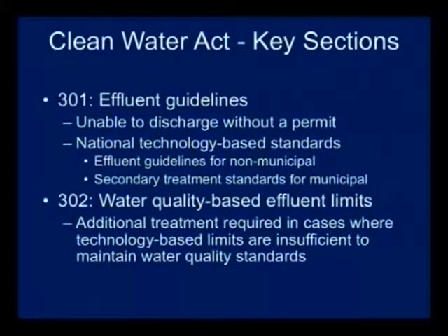On top of that, you may also need to put what is called water quality-based effluent limits on top of that. You first look at the technology-based limits, do the bare minimum that everybody in your industry must do. If your discharge will cause violations of the water quality standard, you have to treat even further such that your discharge does not violate water quality standards. That more advanced level of permitting is called water quality-based effluent limits.